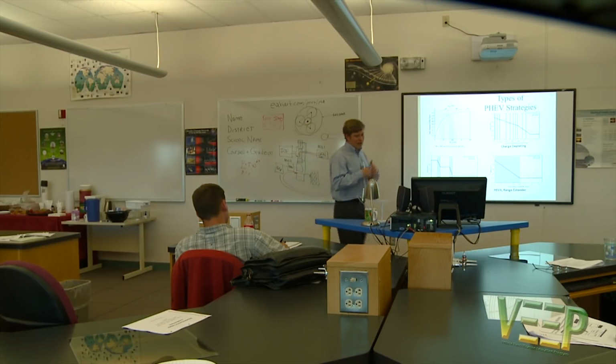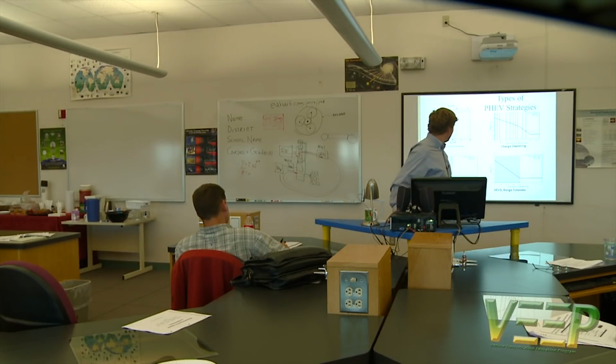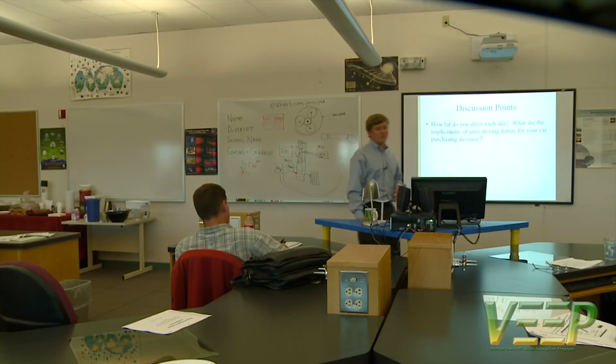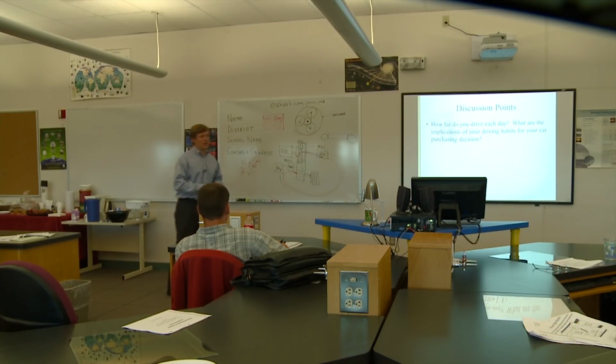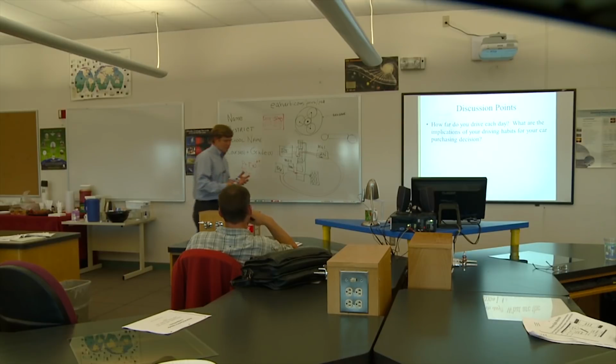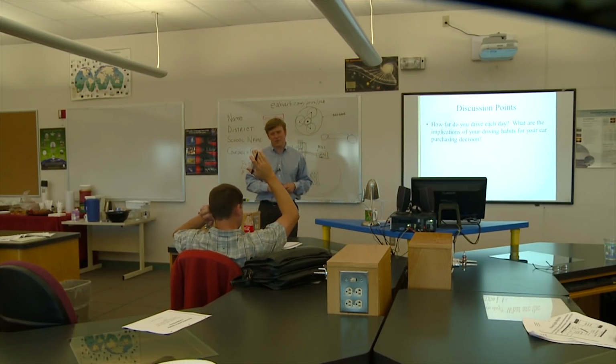You want people who drive every single day exactly the range of your vehicle, and those are the people who will save the most money. I always think that's a really interesting trade-off, because what it really shows is that sizing the battery pack, thinking about how far these cars should drive and how expensive they are, is completely tied in to who the customer is and the way that the customer drives and values electricity and their fuel savings.